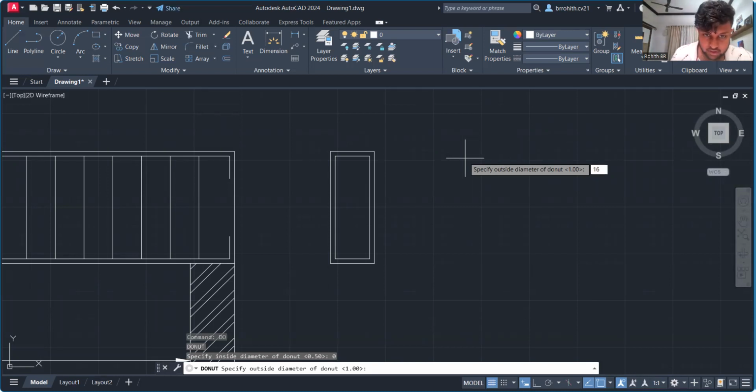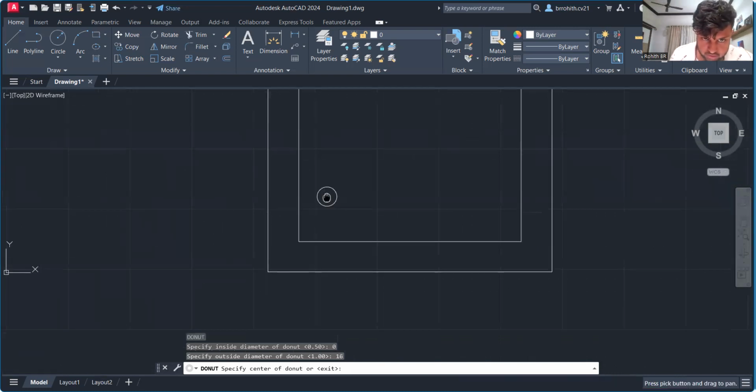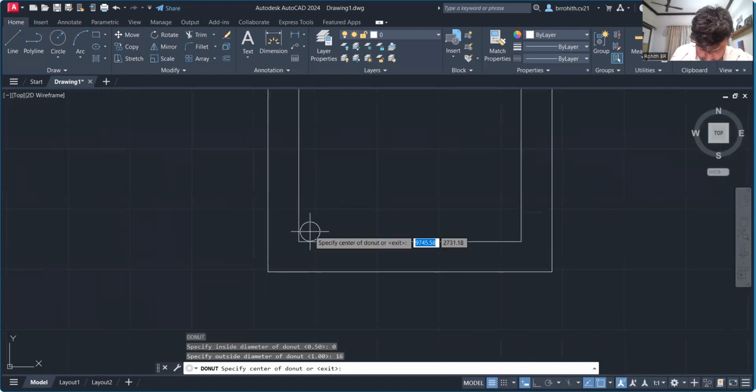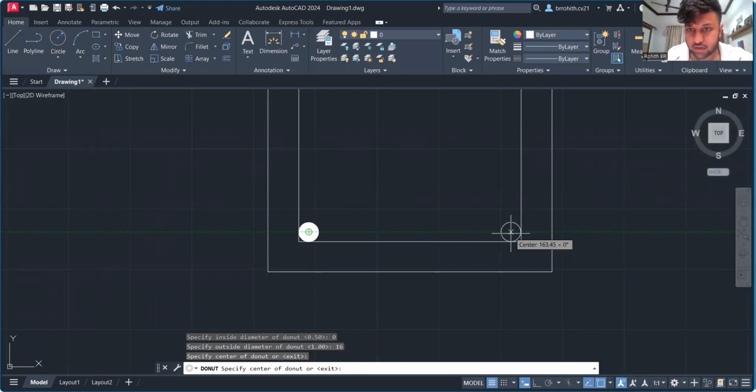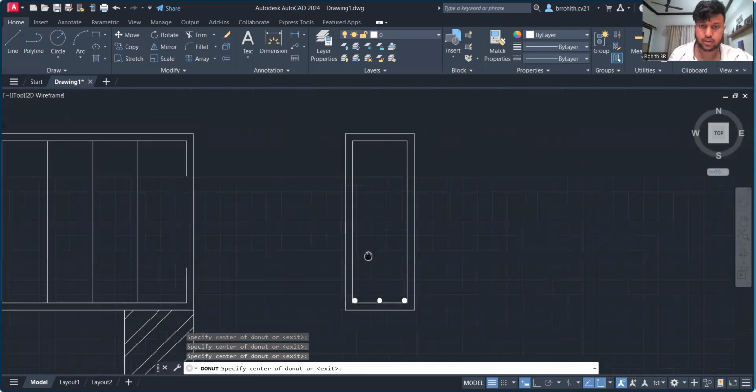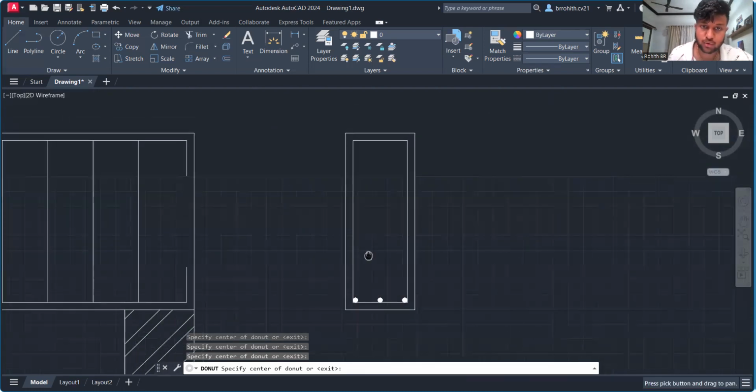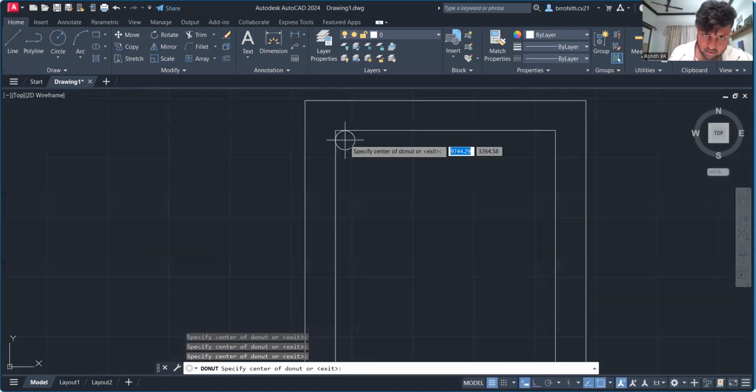And you can specify it at this point, since we have 3 tension reinforcement bars and 2 hanger bars. There are 3 here, one at this corner, one at this corner, and one at the center. It would be the same at the top, but there you give only 2, since there are only two hanger bars.